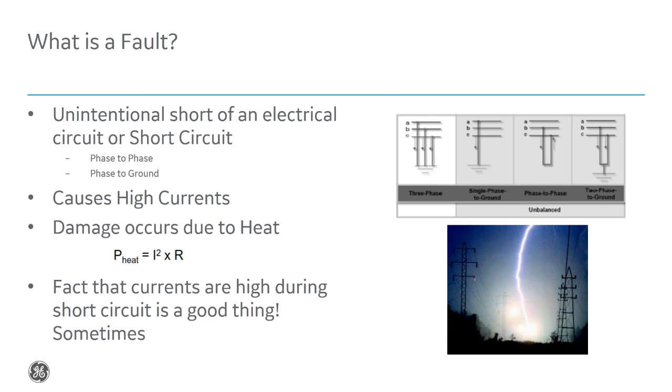So that is the consequence of having a short circuit. It's going to cause high currents in our power system, it's going to cause heating in our power system, and eventually, if it's not cleared, it's going to cause permanent damage to the equipment, transformers, buses, and such.